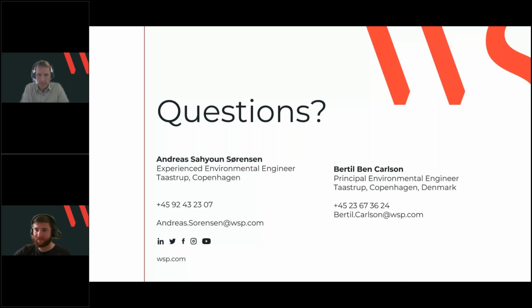Thank you. I will take the last question, and all additional questions will be answered directly by the presenters. Can this system be used when you're removing groundwater during tunneling or mass excavation? Yes, the system can be used in projects where it's necessary to carry out groundwater level lowering. Maybe the part about particle tracking would not be necessary, but the system with loggers sending data continuously to a platform, that would be very good to have.